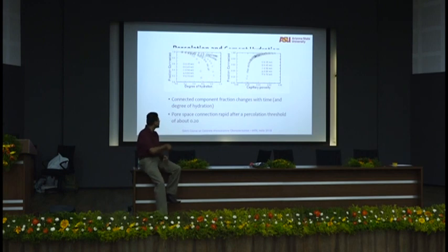Okay, so that's a combination that you have to think of. Also look at the capillary porosity with fraction connected, with nothing connected. Even when you have nothing connected, complete solids, you still have about 18% capillary porosity. Now this number is about 18%. Okay, so remember this value of 0.18 or 18%.